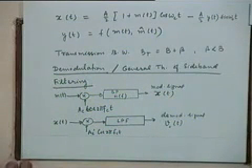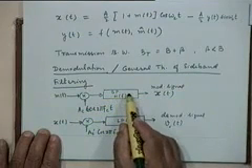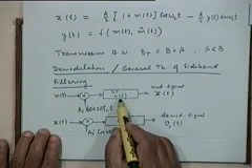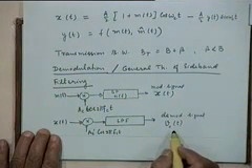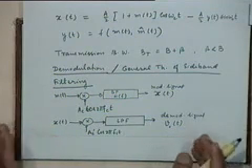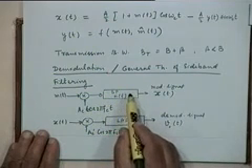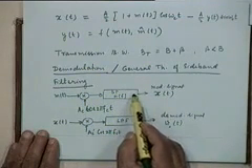The general theory that we are going to discuss addresses the following questions. What kind of band pass filter, or what kind of high pass or low pass filter, should I use at the transmitter? What kind of H(f) should I select so that v_o(t) is proportional to m(t)? Because we are suggesting some rather complicated filtering here in the VSB case.